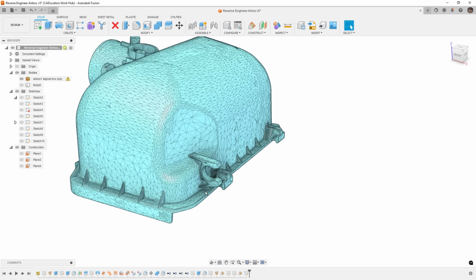And then we'll talk about adding features like support ribs and things like that that are really injection molded features. For a 3D print, we can get away with doing a chamfer and doing some fillets, simply because if you do a 3D print, you can do infill. So let's say this is a 3mm thick part, and you have it set up so that you have a certain number of walls so that you have 3mm of solid.